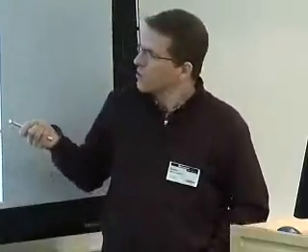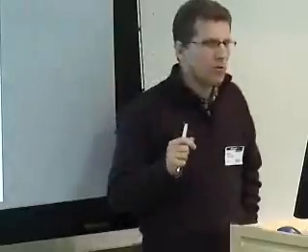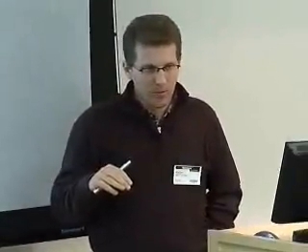For other parts of the chip, yes, you still have leakage, but the main consumer, as I will show you in a few seconds, is cache. So here it is only cache. And you can turn off some parts of the processor so that you reduce leakage. What's the intuition behind why the cache is leaking so much more than the processor? The main reason, I will talk about it just in a few seconds.